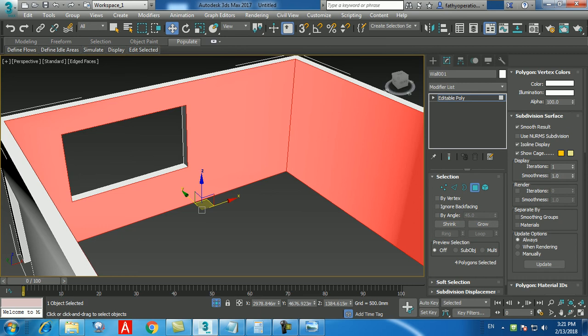But this gap that you made, there is no proper welding. So when you did Pro Boolean, you have these edges. Because when you subtract it, it couldn't understand where to go and do the welding. So it's breaking your wall into different pieces. So this Boolean is a very tough one. If it is not proper, this Boolean can affect. Even for example, I will do the same thing. I'm not welding this one. Let's say AC extended, I'm doing the same issue.